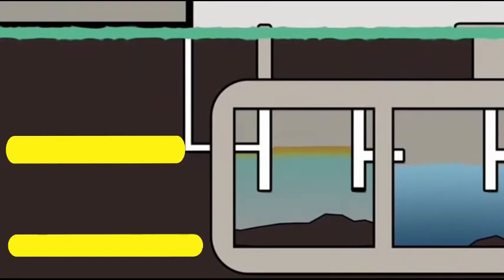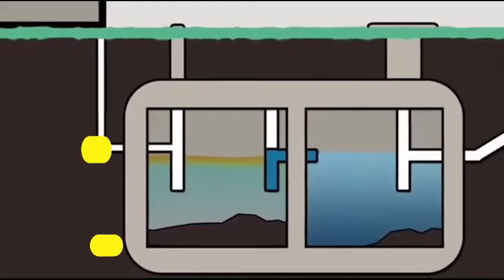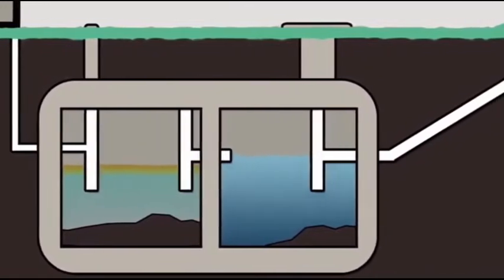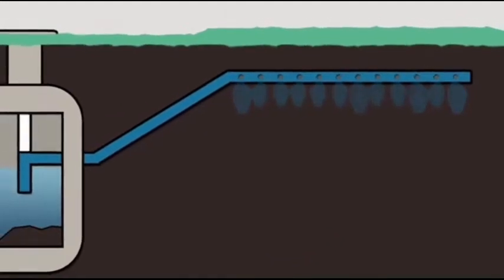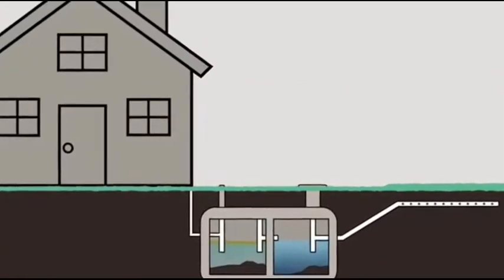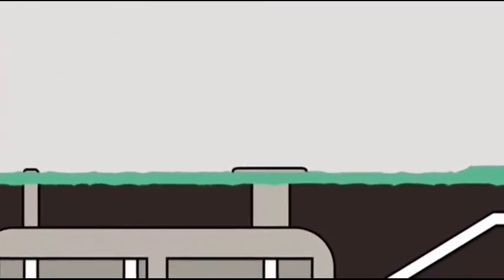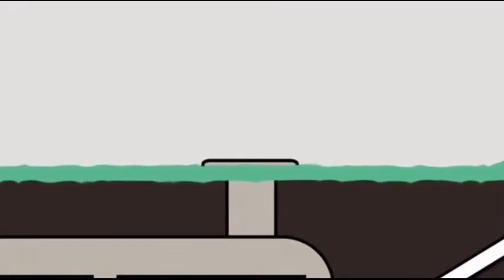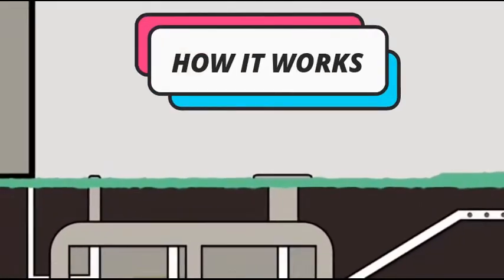The name refers to the construction of the drain field. With this design, effluent is piped from the septic tank to a shallow underground trench of stone or gravel. A geofabric or similar material is then placed on top of the trench so sand, dirt, and other contaminants do not enter the clean stone. Effluent filters through the stone and is then further treated by microbes once it reaches the soil below the gravel or stone trench. Gravel or stone systems are relatively large in overall footprint and may not be suitable for all residential sites or conditions. So how does it work?